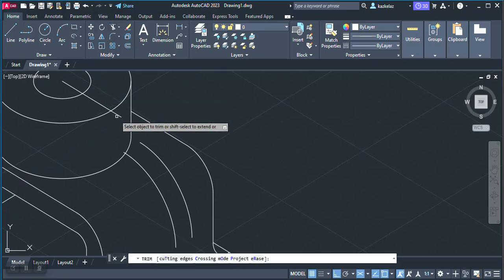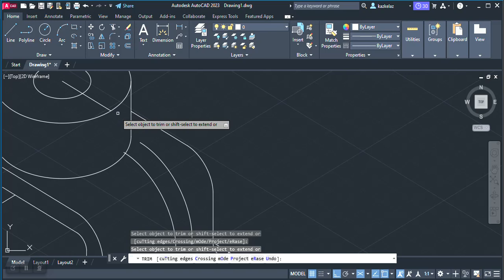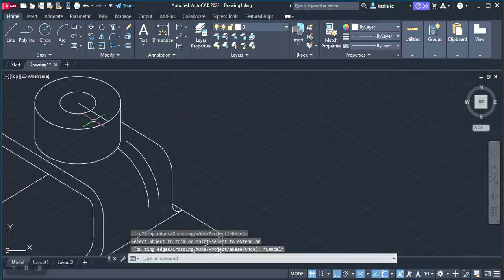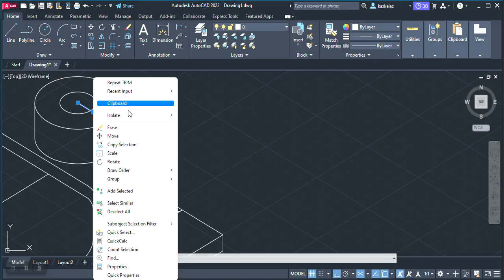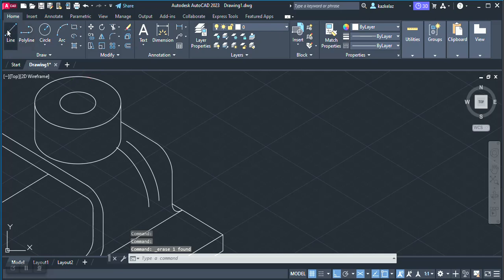So let's select elliptical arc, and select a circle. Let's go to that endpoint. Once it says endpoint, we move away along that line. Then we type, we know its radius is 13, so we type 13. We know its center is going to be there. Now we know its radius, 13.